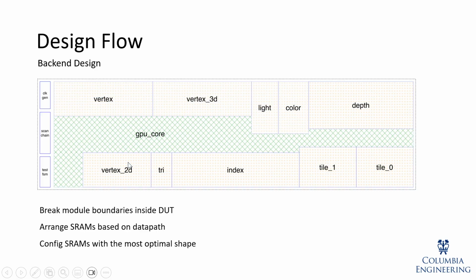We ran the entire design flow several times, modifying RTL code as mentioned previously, and made other improvements in the APR stage. First, it is the placement of the SRAMs. Now we place them according to the data path and then adjust it a little bit to allow the best routing strategy for the tool. It is actually a really critical step because at first we just placed them randomly on the chip and what we got was 2 days running the APR with thousands of DRC errors.